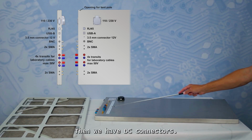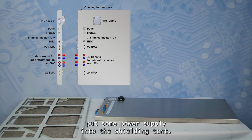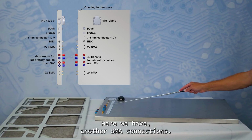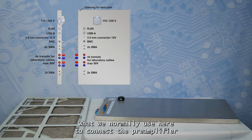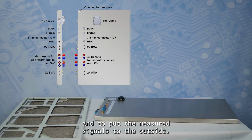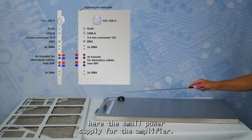Then we have DC connectors, filtered DC connectors to put some power supply into the shielding tent. Here we have another SMA connection. Then we have here a BNC connector, what we normally use here to connect the preamplifier to the reference plane and to put the measured signals to the outside. Then we have here the small power supply for the preamplifier.